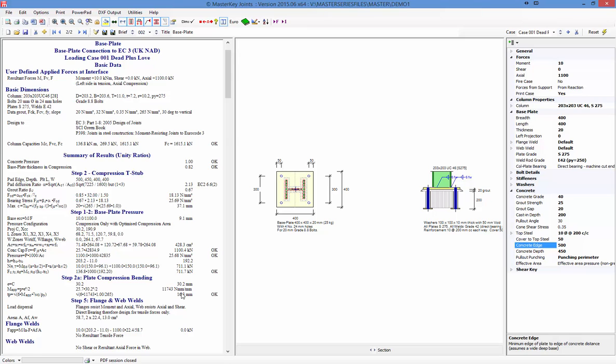We are using a 20mm plate, so we cannot get any lower than 16.3, because we can't go to 15, that would fail. If I put that back to 100, we would see that we actually now need a 19.2. So in some instances, paying attention to this distance will give you an enhanced capacity of your section. So that's a very simple base plate, done in 2 minutes. No stiffeners, no nothing required.